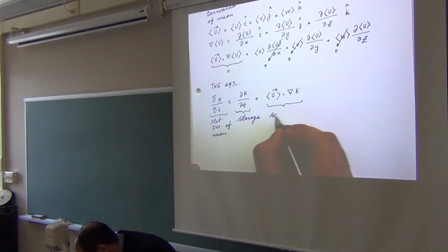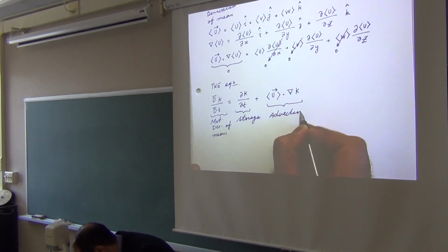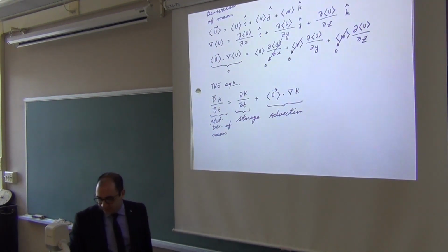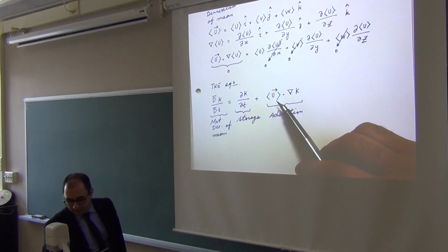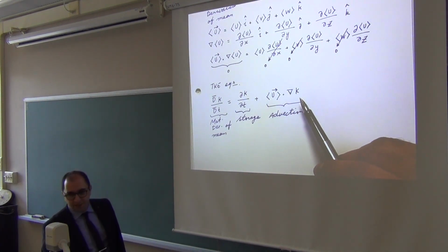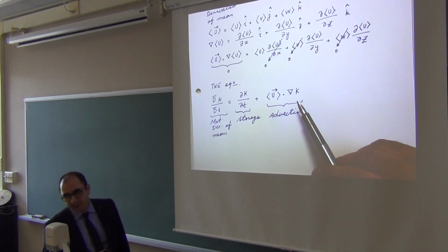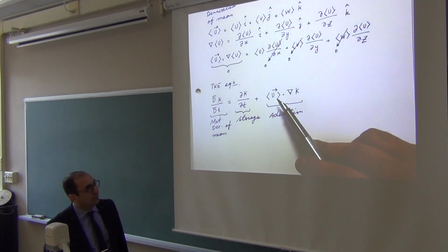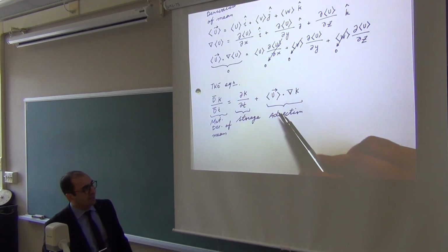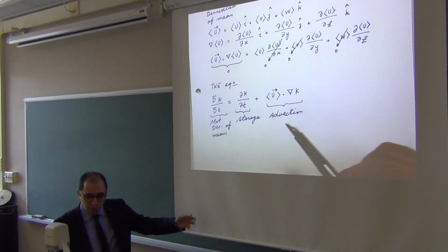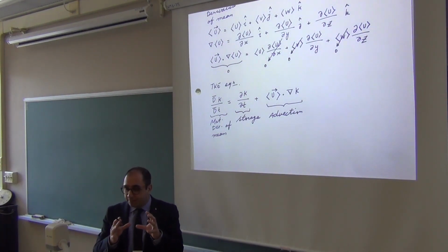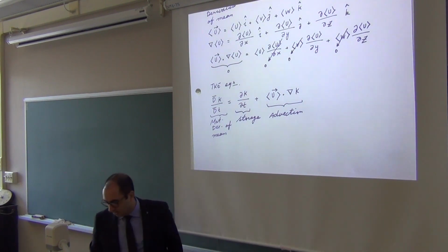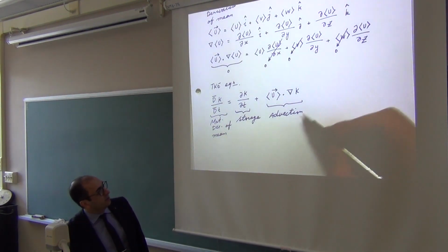If you notice, there is a similarity. In any advection term, you always have this vector u. Regardless of the equation being for K, epsilon, temperature, passive scalar, whatever it is, this is always u, because it's the velocity that advects a parcel of the fluid and takes it around. It could take around a parcel of temperature, or a parcel of momentum, or a parcel of kinetic energy, whatever it is. So this is always u.